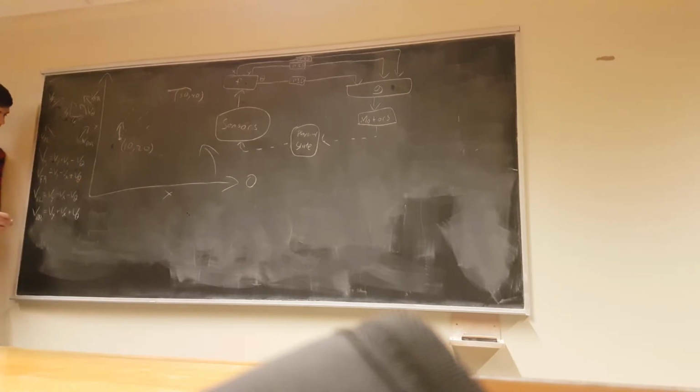The issue here is that there's a maximum voltage that you can apply across the motor. That's the voltage of the battery. Often what we'll do is this won't actually be voltage, it'll be percentage of the maximum voltage. Or proportion, meaning that 1 means full throttle, right? So if 1 means full throttle, what do you do if one or more of these adds up to more than 1? If you don't do anything, what the underlying system between our code and the motors does is if it's more than 1, it just assumes it's 1. If it's less than -1, it assumes it's -1. So it just caps it to the range -1 to 1. Okay?